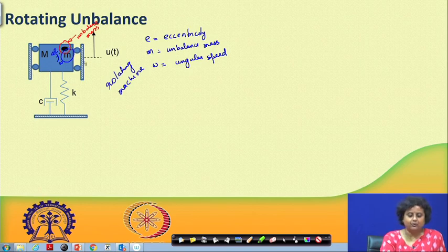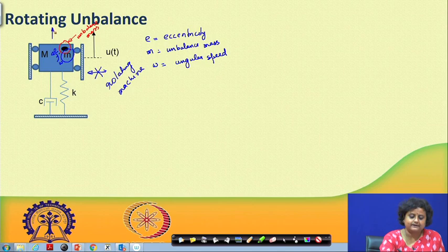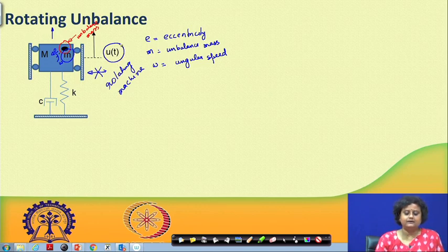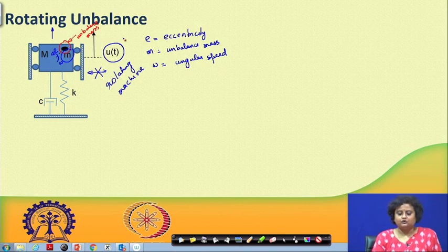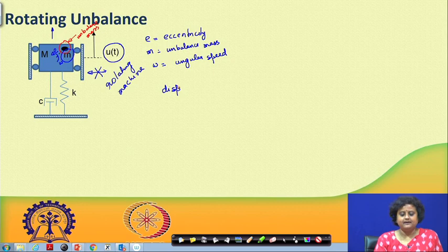Because of these two supports, these two constraints, it cannot vibrate horizontally, so this vibration is cancelled out. So, we are constraining the horizontal vibration. It is only allowed to vibrate in the vertical direction. Let us say that the displacement in the allowable degree of freedom of the capital mass M is u(t). So, the capital mass M is experiencing a displacement of u(t).